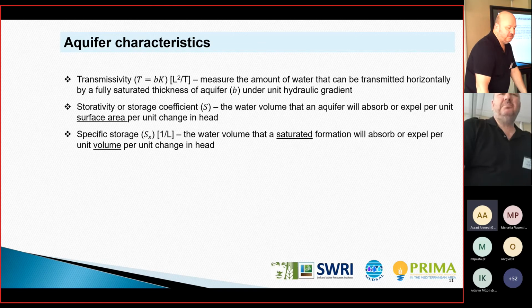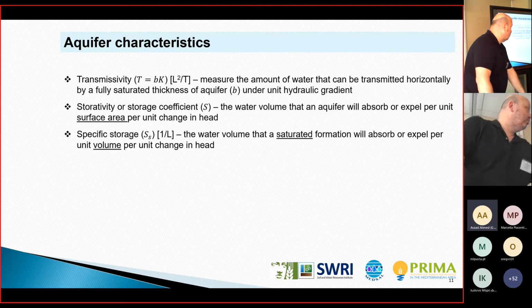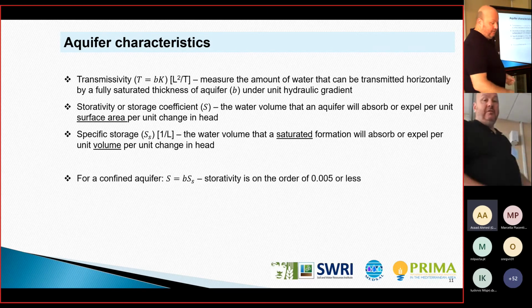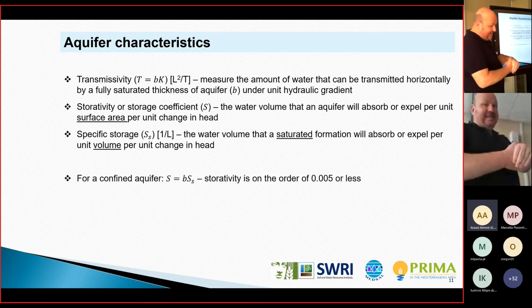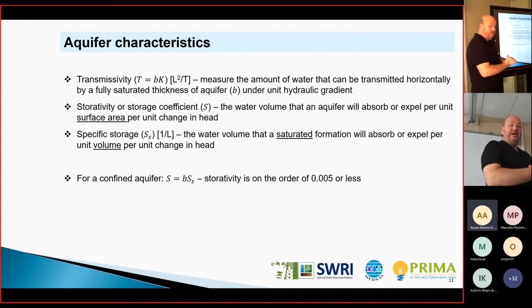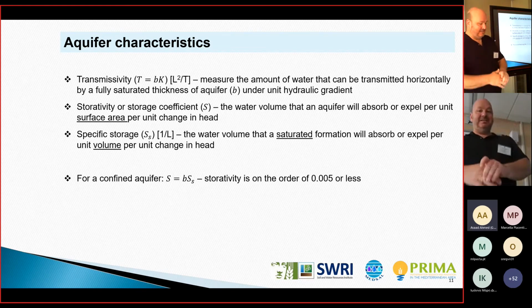A similar concept is the specific storage, which has units, and is the water volume that the saturated formation will absorb or expel per unit volume per unit change in head. For a confined aquifer, the storativity is usually taken as the product of aquifer thickness and specific storage, and is usually of the order of 0.005 or even less.